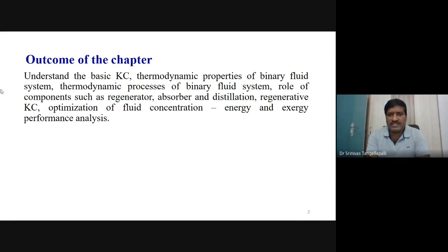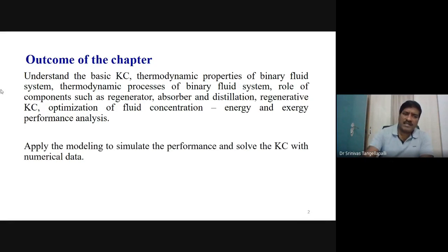So this evaluation includes the energy analysis using the first law of thermodynamics and also exergy analysis using the second law of thermodynamics. So we are extending this Kalina cycle study up to the level of numerical solutions. We should be able to apply this formulation to the process and Kalina cycle, and finally we should be able to solve some numerical problems to find the power generation from the Kalina power plant and the efficiency, like energy efficiency and exergy efficiency.